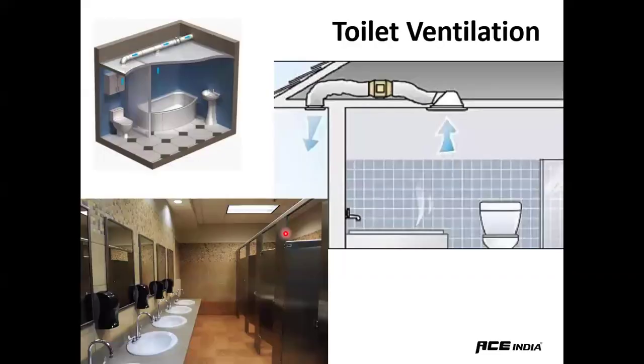Inside the toilet you can see some gaps, isn't it? These gaps are for infiltration. That means the outside air enters through the bottom gaps of your doors once the existing air is pushed out to the atmosphere. That's how infiltration happens in a negative ventilation setup. Is it okay?